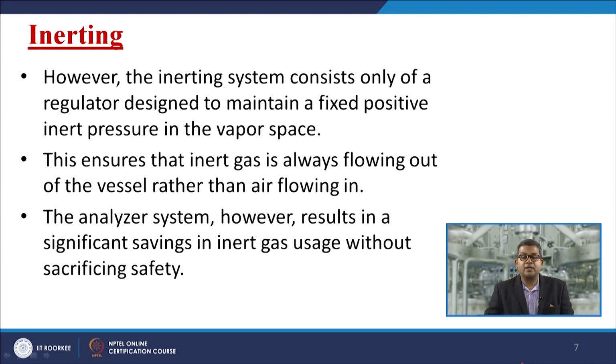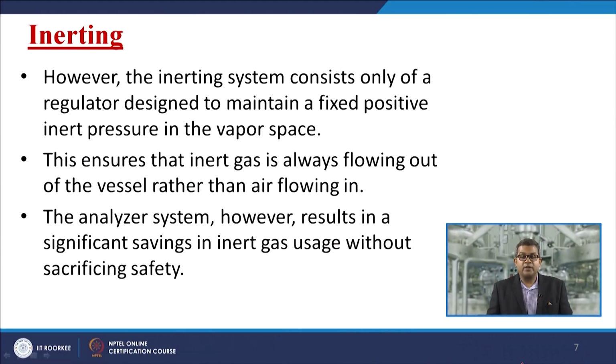However, the inerting system consists only of a regulator designed to maintain a fixed positive inert pressure in the vapor space. Now, this ensures that inert gas is always flowing out of the vessel rather than air flowing in, so that the impact of air is minimized. The analyzer system, however, results in a significant saving in inert gas use without sacrificing safety.